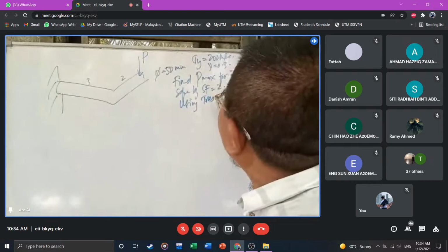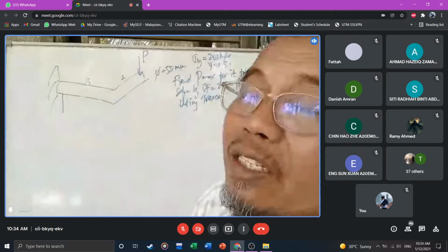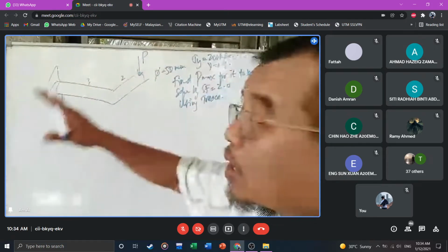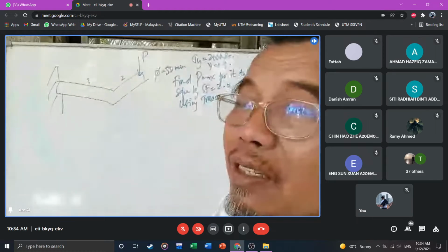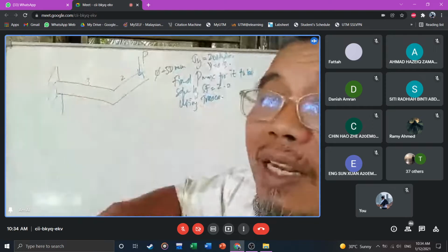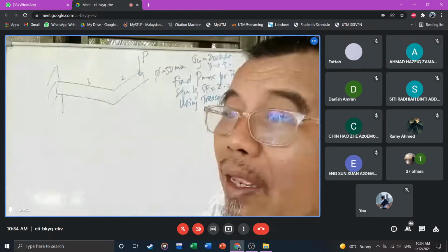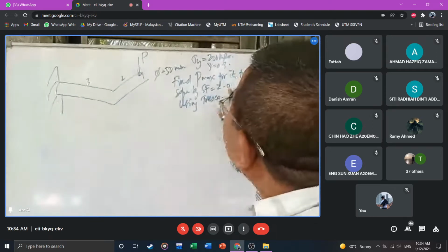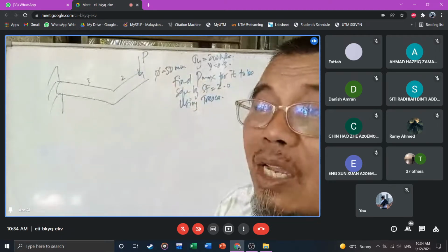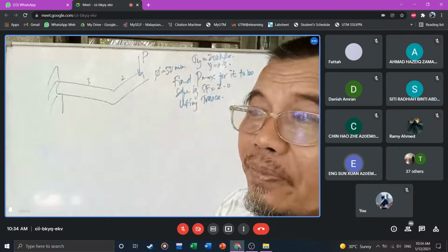I like to use Tresca because it is easy for calculation. But even though you show the graph there, Tresca and von Mises are not very far away, right? The border. Remember the border there? Tresca and von Mises are not very far away. So this is metal. What is the P there? So this is a reverse question. Are you with me? Yes.